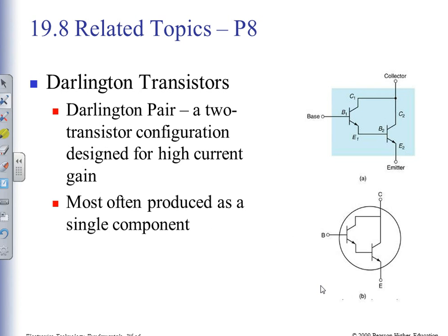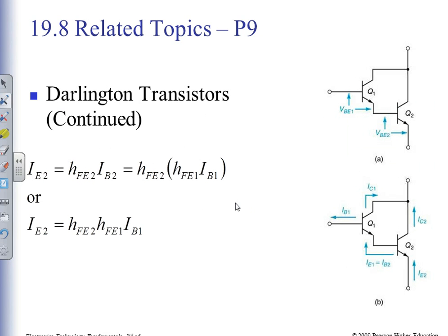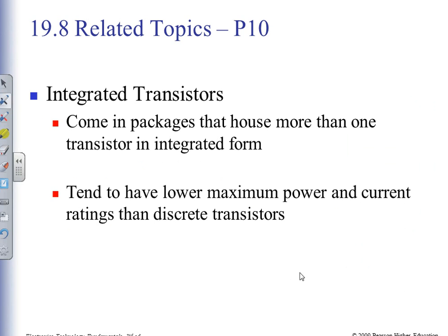Darlington pairs. Oh, isn't that lovely? So I can make a big power transistor and have an itty bitty one turn it on, and that would be a Darlington pair. Darlington pairs are made together. They're not something that are separate. You buy them together. If I'm going to have a power transistor, you can bet it's a Darlington pair. You can calculate the current at the emitter, and there's a calculation for that. Okay, well, we'll never remember that.